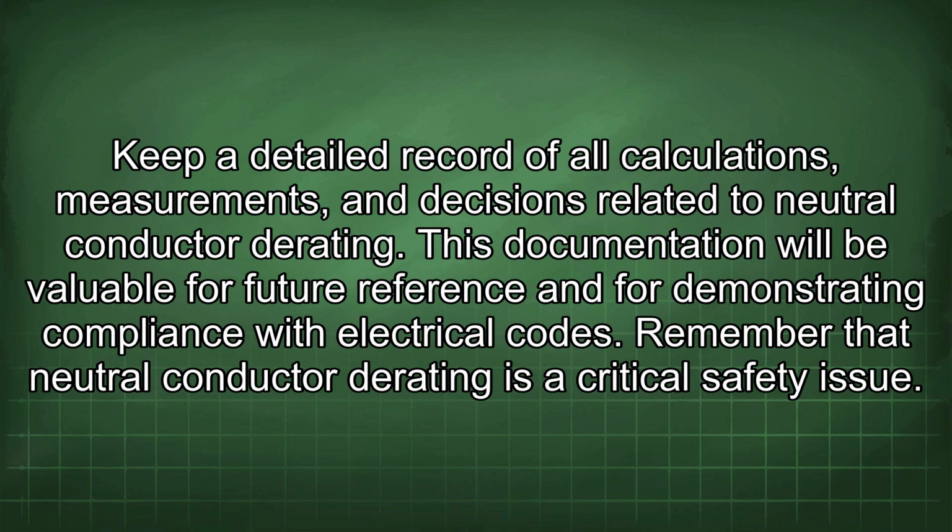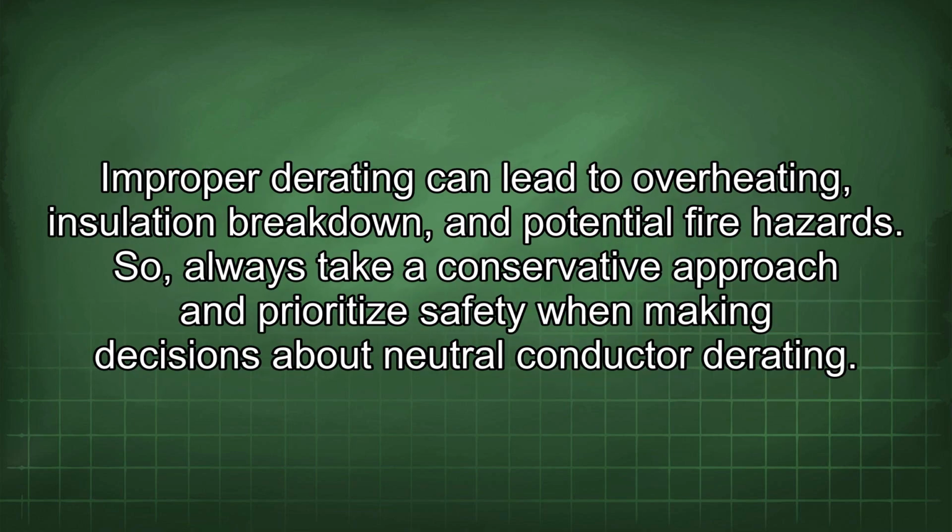Remember that neutral conductor derating is a critical safety issue. Improper derating can lead to overheating, insulation breakdown, and potential fire hazards. So, always take a conservative approach and prioritize safety when making decisions about neutral conductor derating.